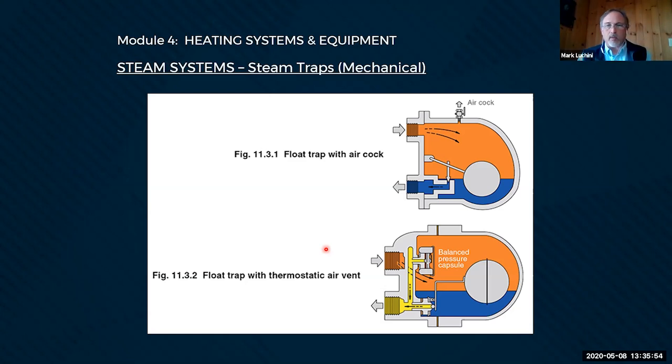The air's got to go somewhere. This is one of the ways that it gets out. So it hits a floating thermostatic trap, which will keep letting air pass out until it sees steam. And once it says, okay, I'm at 212 degrees in here, I shut. Now nothing can get through except condensate, because the steam is trapped by the condensate at the bottom.